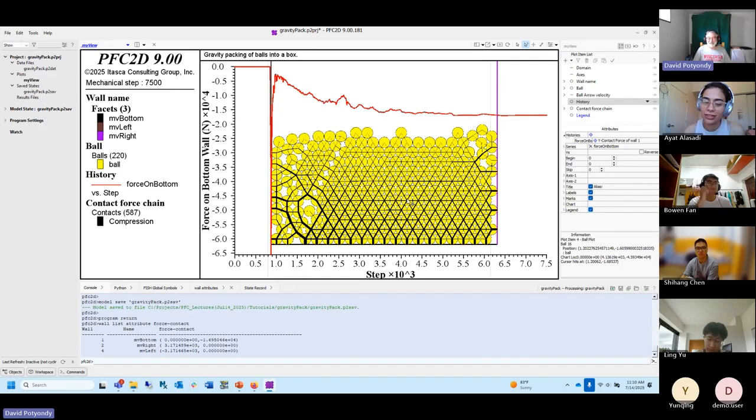So that's why a granular material is not like a fluid. If that was water in there, nothing is transferred to the walls. So the entire weight, the pressure, this has to do with pressure. When you first start looking at granular material, I had assumed that the pressure on the bottom was just a uniform increase with depth, just like water. And because of these effects, it's not. Okay, so thank you for your attention.